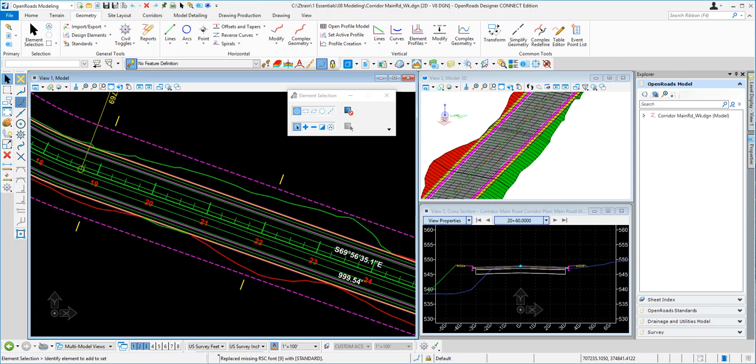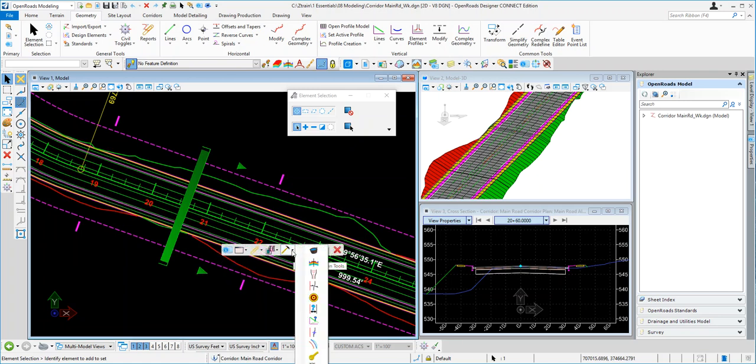Okay, now that the template is set up with the parametric constraint label on the template point that we want to move, let's go ahead and add the values and put it into the corridor. So we are going to go to the corridor here, and we're going to add it right in this area between 1920, 21, 22, just as an example. So we're going to go to the corridor, go to the flyout, go to tools, and then create parametric constraint.